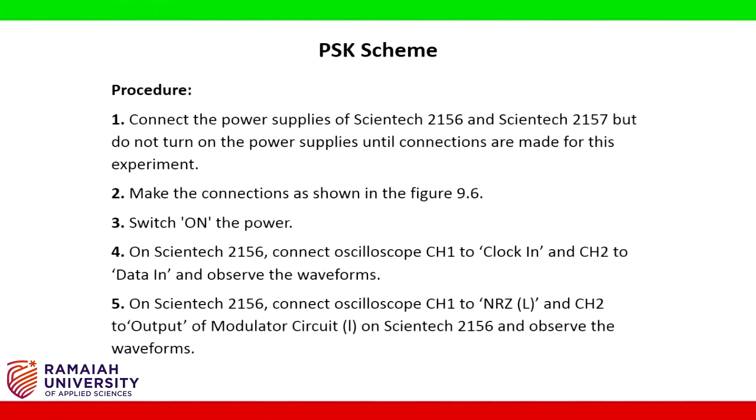The procedure is connect the power supplies of Syntec 2156 and Syntec 2157, but do not turn on the power supplies until connections are made for this experiment. Make the connections as shown in figure 9.6. Switch on the power. On Syntec 2156, connect oscilloscope channel 1 to clock in and channel 2 to data in and observe the waveforms.